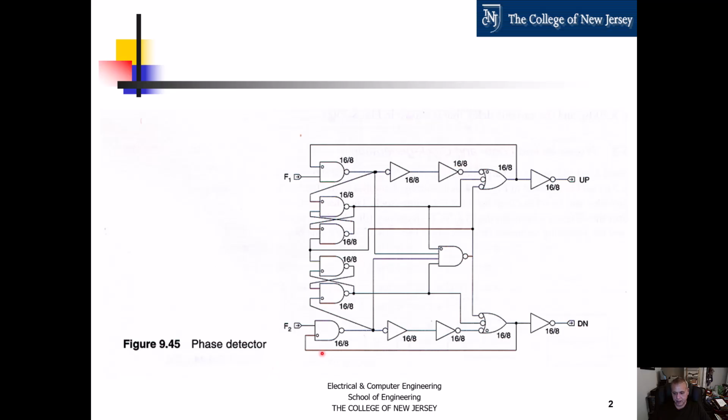schematics. So in this case, when we see these numbers by this gate, we have a number of 2-input AND gates, we have a 4-input AND gate, and we have a couple of 3-input AND gates, and a number of inverters. These are NAND gates as well. It's just different symbology.